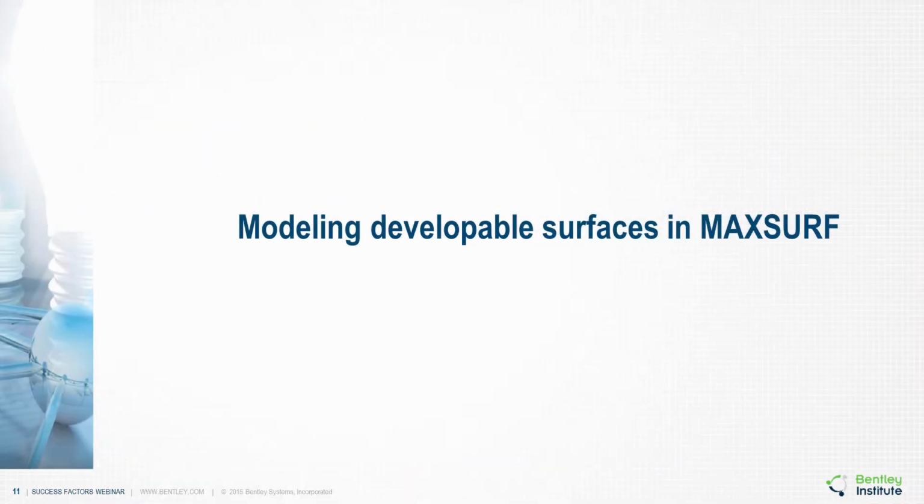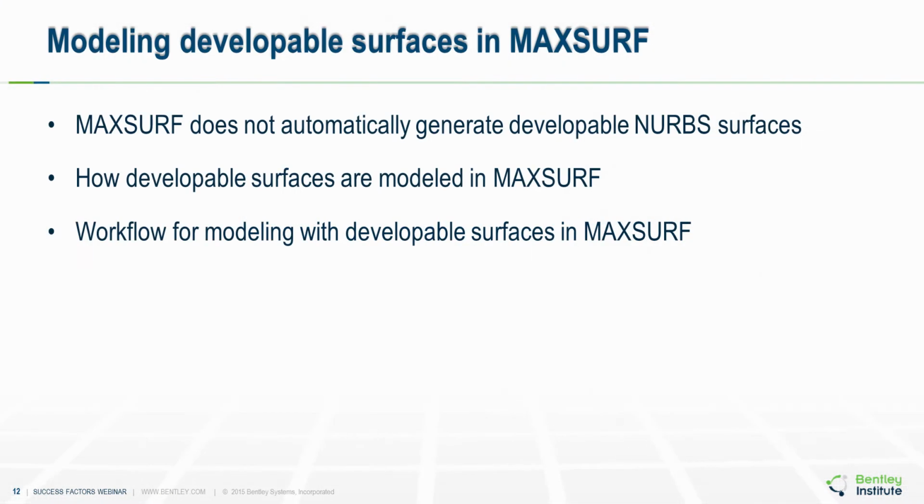So now we'll look in a little bit more detail at how we achieve this in MAXSURF. So the first thing to bear in mind is that MAXSURF does not automatically generate developable NURBS surfaces. It provides a lot of tools, but it doesn't actually generate the NURBS surfaces as developable surfaces automatically. So we'll look at how the developable surfaces are modelled in MAXSURF and then the workflow that we use for actually modelling these surfaces.